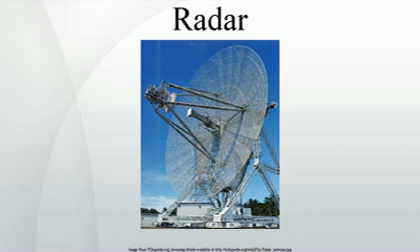Marine radars are used to measure the bearing and distance of ships to prevent collision with other ships, to navigate, and to fix their position at sea when within range of shore or other fixed references such as islands, buoys, and lightships. In port or in harbor, vessel traffic service radar systems are used to monitor and regulate ship movements in busy waters.